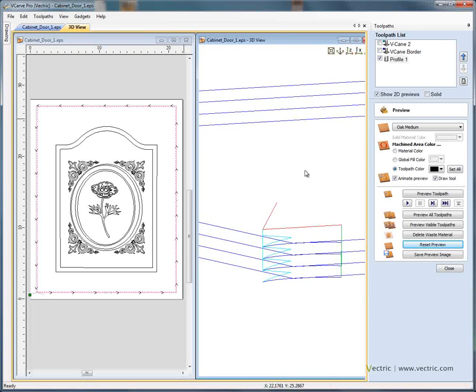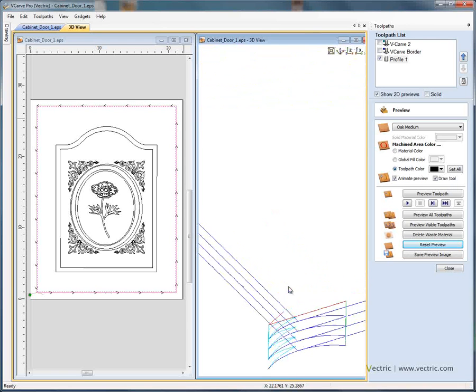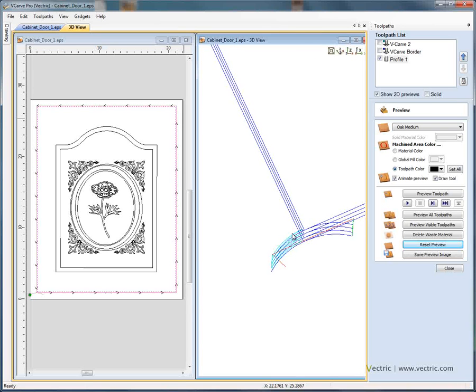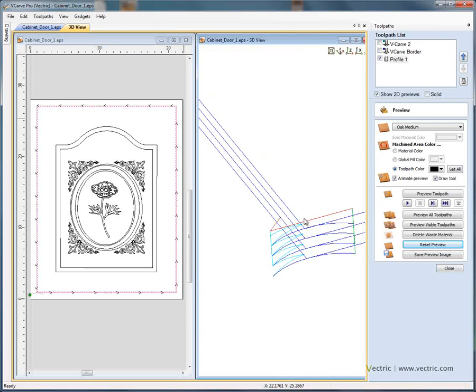You can see the toolpath is going to come across to the start point. It's going to ramp in, zigzag down, but only over the portion of this arc in. So it's going to zigzag down to the first level, 0.25 deep, profile machine around. Then it's going to zigzag down ½ inch deep, profile round again. So we're forcing the plunge moves to ramp instead of plunging vertically.